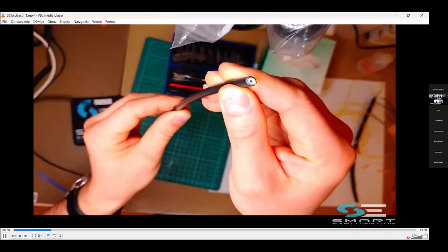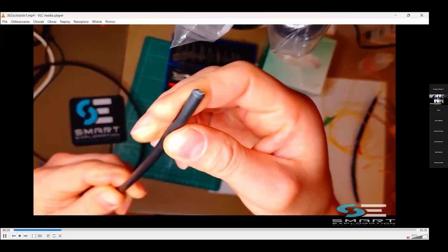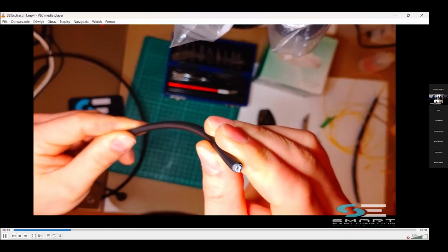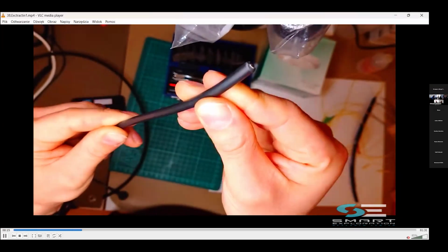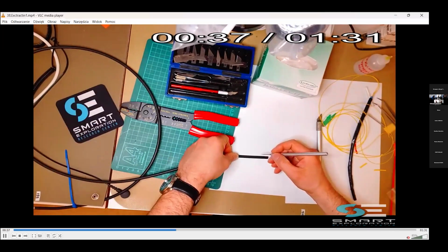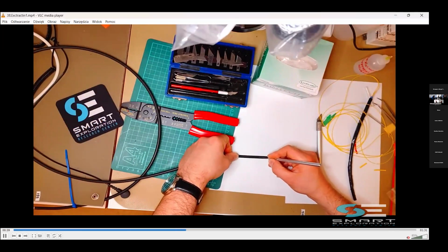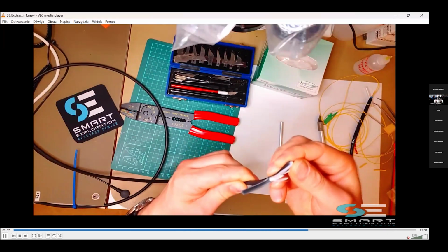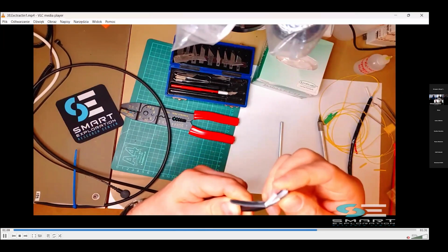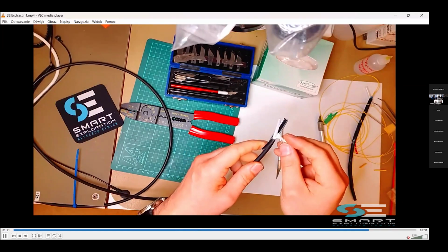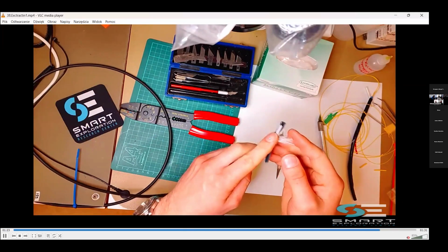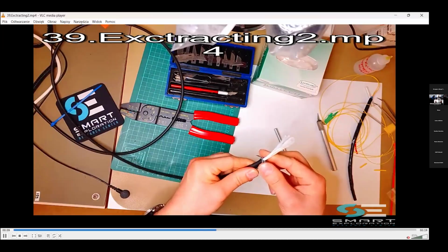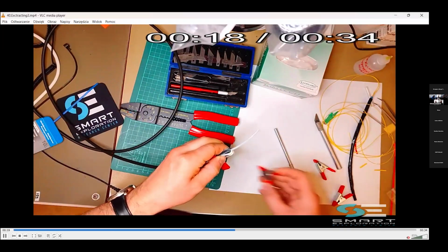And here is shown very quickly how we can extract the fiber optics from the typical cable that we're using in the ground. We need some scalpels, and this maintenance takes time, because very often we have some additional layers. We have some additional Kevlar fibers. We have some additional plastic material.